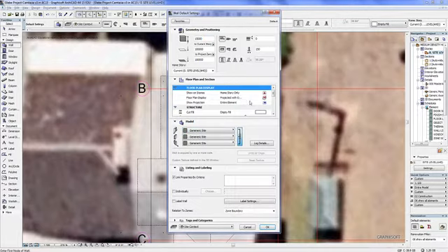So we're just going to change it to generic site. Then all the other parameters at this stage are fine. Press OK. We just made sure that it's on site context. Press OK. Now, we need that 100mm offset. So we need the assistance of the drafting aids, because if we were going to just draw the wall now, it's just going to draw the wall with no roof offset. It's just going to draw it along the edge of the perimeter of the roof footprint now.